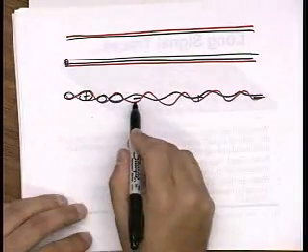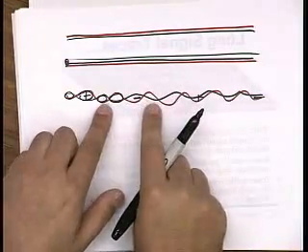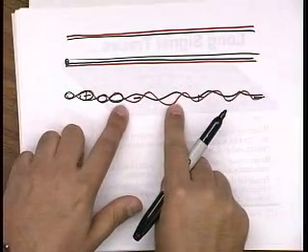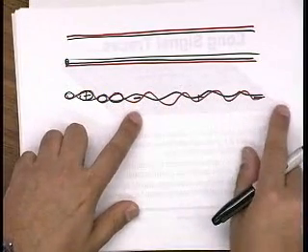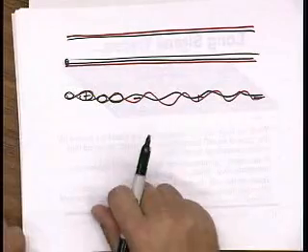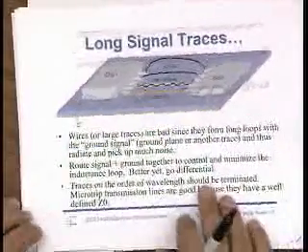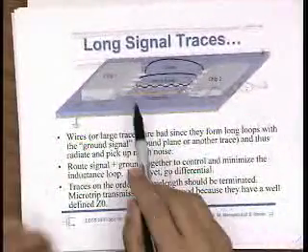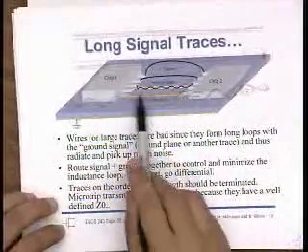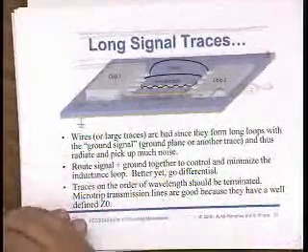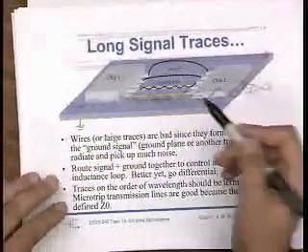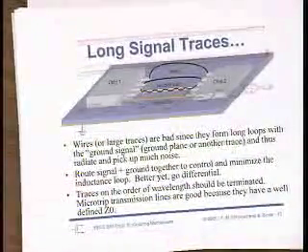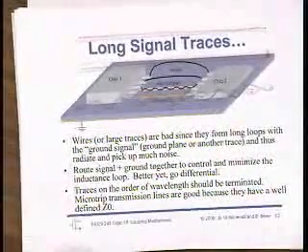So this is plus, minus. Then you just shift over and the same thing happens here. Shift over and the same thing happens here. Right? So twisted pairs are pretty nice for that reason. We don't use them much, though, if you're talking about building a board. First of all, because you don't want to use wires, right? They're not as reliable as traces on your PCB.